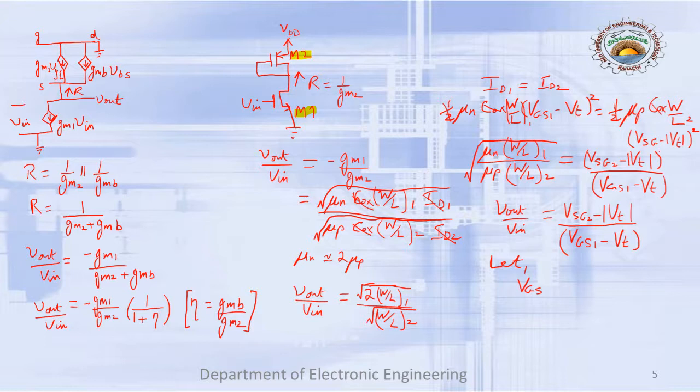And that's why if we use a PMOS transistor, that would be a better decision, because we can actually have transistors which are somewhat smaller in size, and we can still achieve the same gain. So that is why we use this mu n over mu p, the mobility difference, for the gain. Okay. So I hope it is a bit clear.